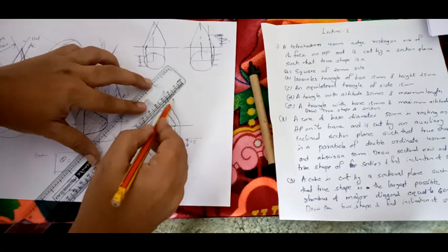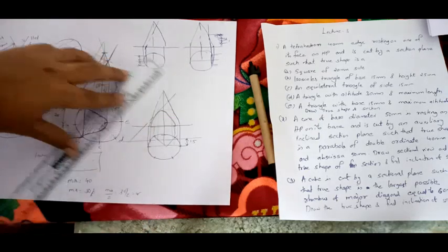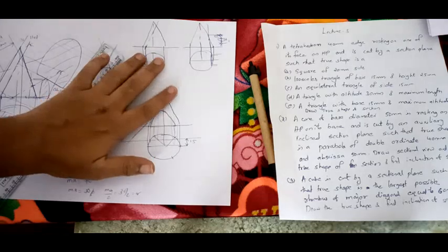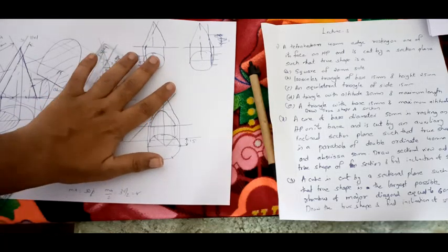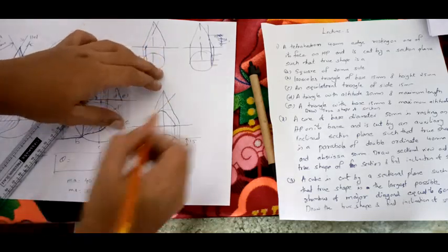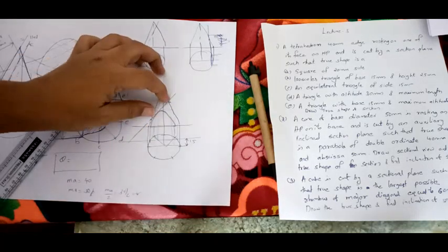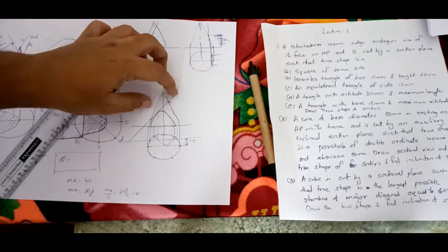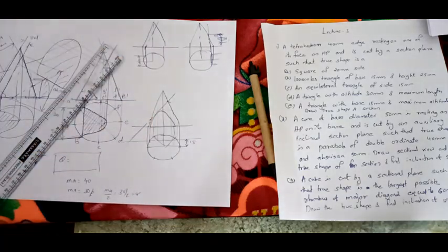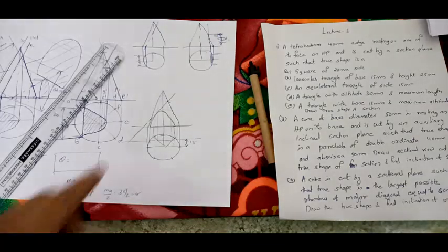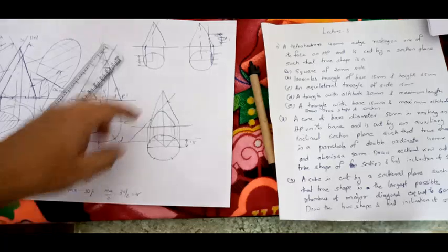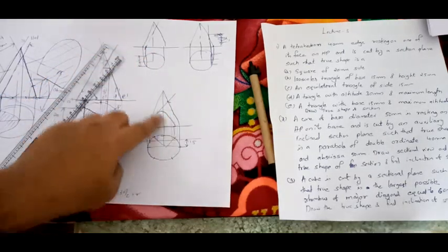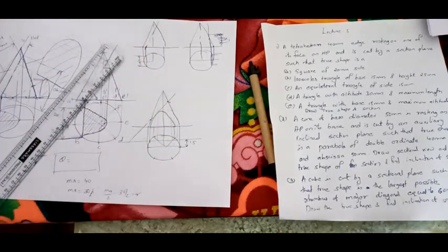So if it is equal to 40 mm, I will draw like this. So by trial and error method, you have to place the scale tangential and in such a way that from this point to this point, the length should be equal to 40 mm and this line should be tangential. By trial and error method only you will be able to draw this. So this is your section plane. After drawing this, these all were light. So after drawing this, correspondingly obtain the top view and draw the true shape.